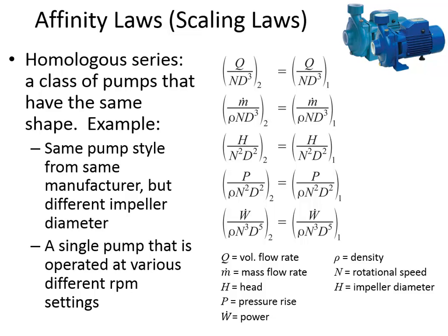What these affinity laws allow you to do is compare the performance of a pump under one situation with that same pump under different circumstances. And so for these variables that are defined here, volumetric flow rate we already know about, mass flow rate we already know about, head here, what we're calling H on this page, we've been calling pump head on the examples we've been doing. So you can put in parentheses here that this is really H sub P. These are pump analogies, and the pump head is what we're talking about.